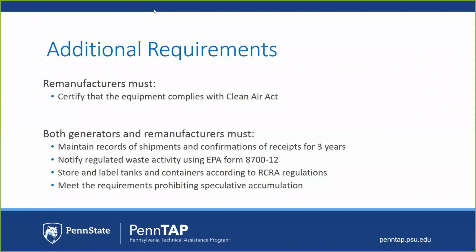Make a regulated waste activity notification using EPA Form 8700-12. Store and label tanks and containers according to RCRA regulations, and ensure that spent solvents are meeting applicable emission standards and meet the requirements prohibiting speculative accumulation.